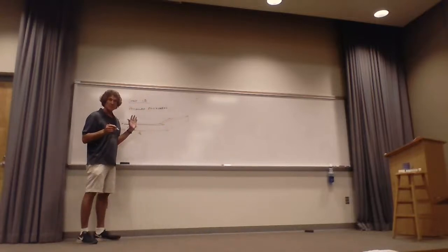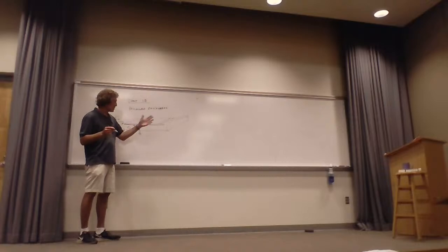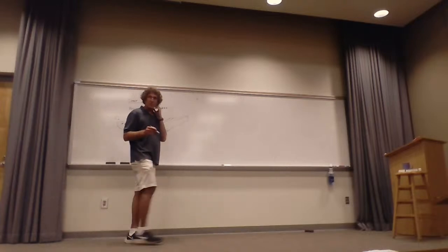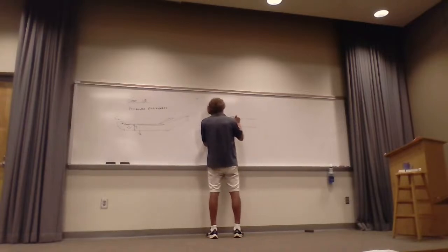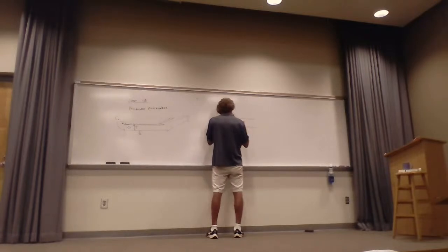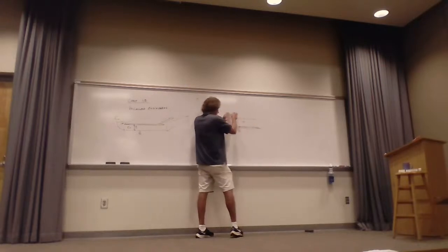Y'all with me? That will connect circuits. Most of the top of the board will be vacant of copper, but there'll be connections. If you actually looked at the side view, you would see lines that have a certain width and a very thin height, which I call H, and then the thickness of the dielectric would be T, with some relative epsilon, and this would be grounded, with a layer of copper on the bottom, but lines of copper on top.